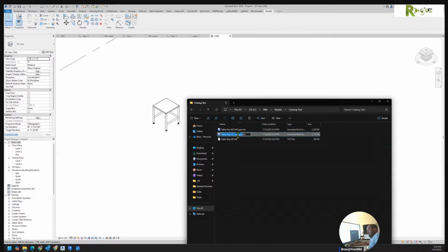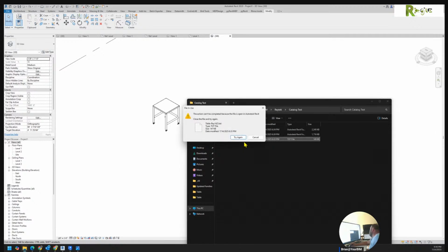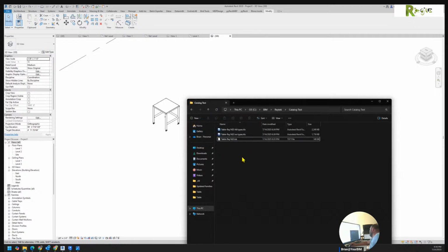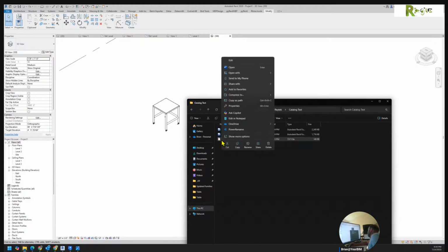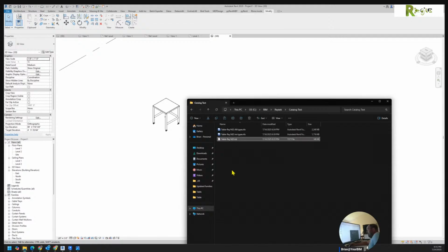I can simply take that name, and as long as I have a text file with a matching name, oh, you know what you have to do? I know what I'm going to have to do. All right, this is where it gets real frustrating. That text file becomes locked up because of its association with Revit. So you can't do that rename. But that doesn't mean I couldn't go copy, paste, take that guy, rename him.